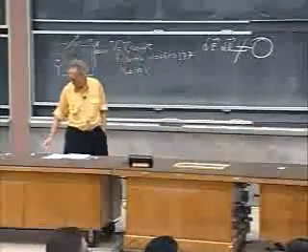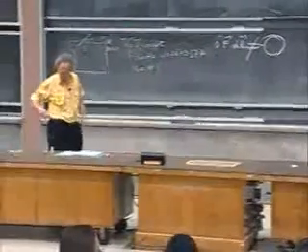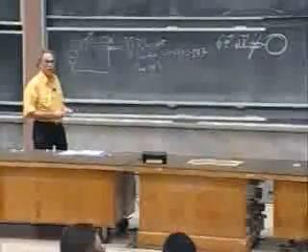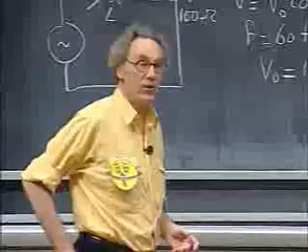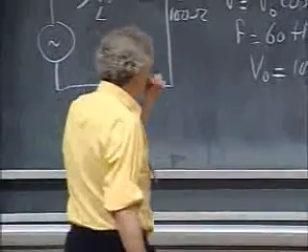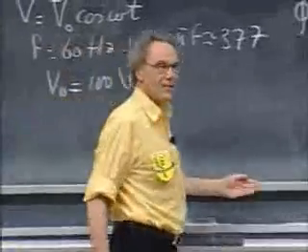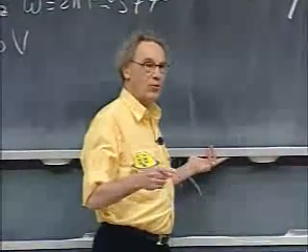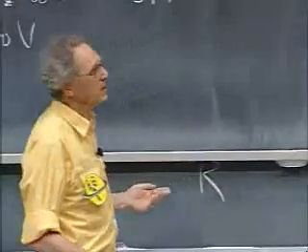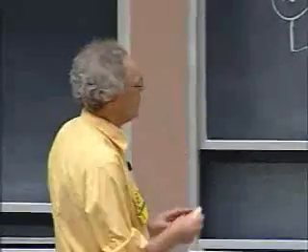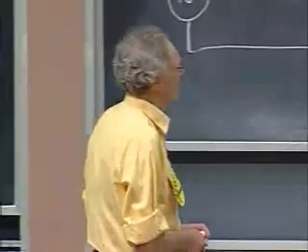You must deal with Faraday's law, no matter what your textbooks tell you. Kirchhoff's loop rule does not hold. And if you do that correctly, you end up with the right differential equation, which happens to be the same one that those people find who do not understand the physics. They massage things in such a way that they get the same answer.